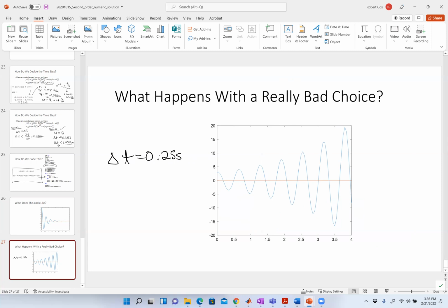This can happen, right? And I've seen people do this in the real world, where they're trying to put some kind of a filter into an embedded system or something like that. They chose a time step wrongly, and all of a sudden you get what I would call a numeric explosion, where this value should be getting smaller, but it's actually getting bigger. And that's going to cause problems in your code, obviously, if you're using this for something.